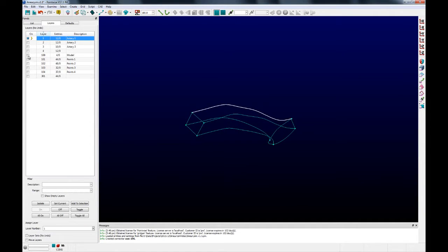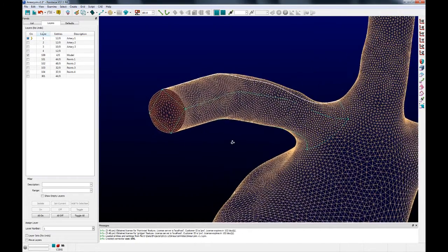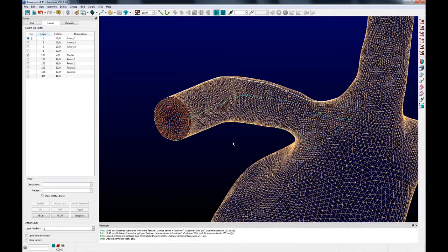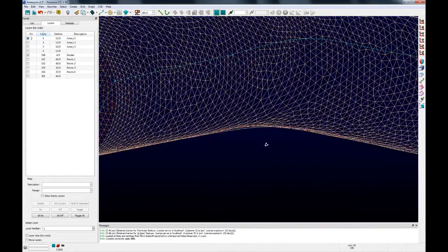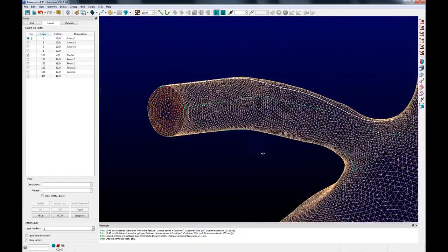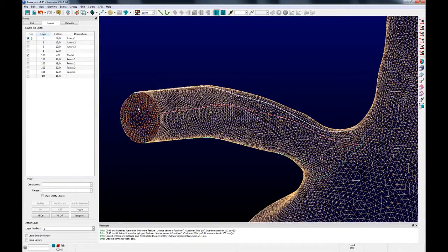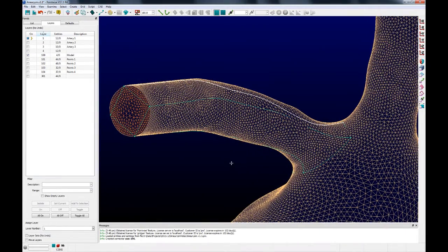However, at this point, the wireframe is not exactly conformal with the mesh. Or with the model, I apologize. The overall structure is close. We've got the right general shape, it's in the right vicinity, and point to point it's matched, because remember that each of those control points lied on the database surface. However, the overall wireframe is not conformal to the mesh. So what we need to do is actually project it onto the underlying database.